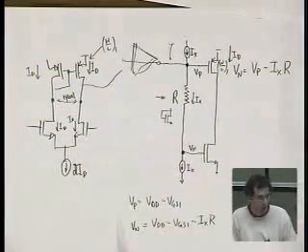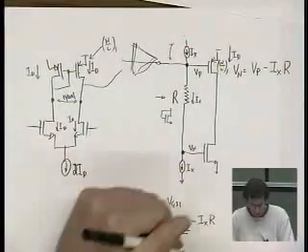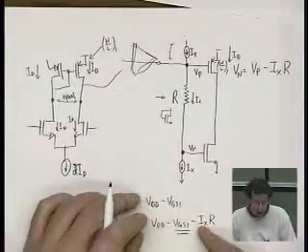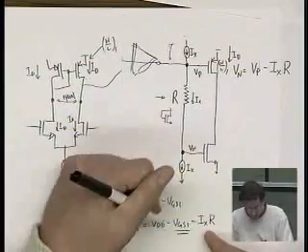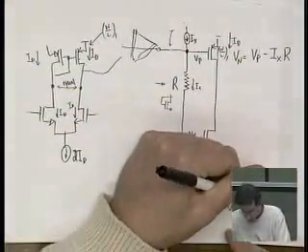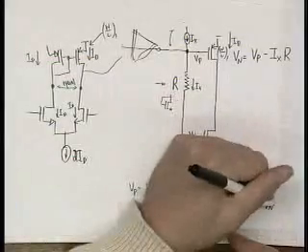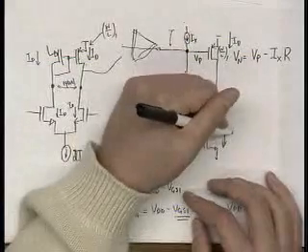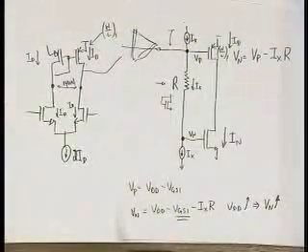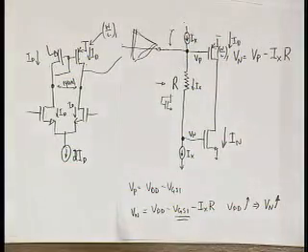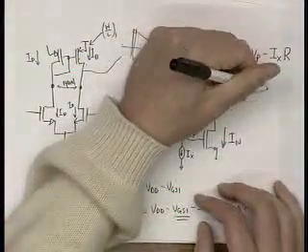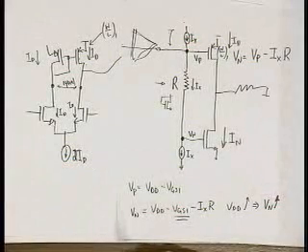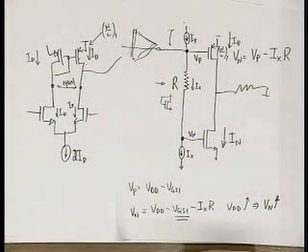So as VDD goes up, this is going to stay the same. And if IX is constant over supply, that means as VDD goes up, VN goes up. And as VN goes up, the current in this will also go up, and it'll go up as a strong function. And that's the exact question that you're asking, right? So the question is, how do we get around that? How do we solve that? Does anyone have any suggestions?